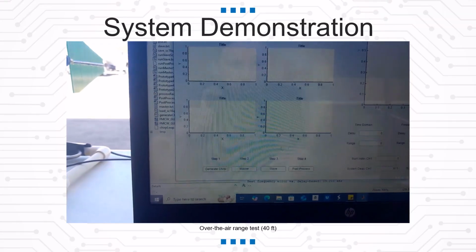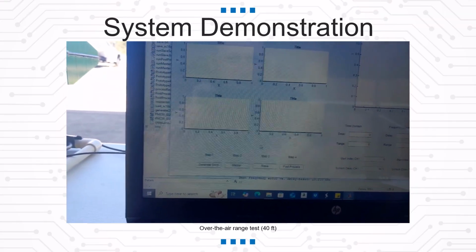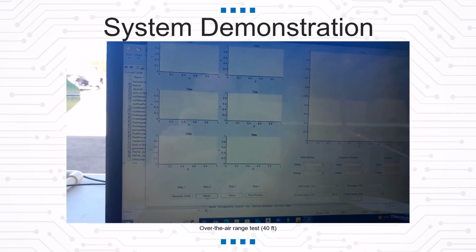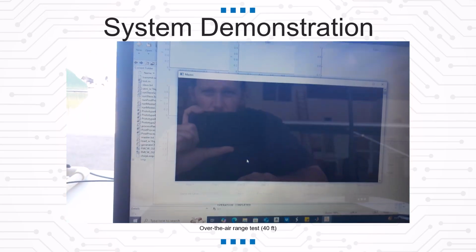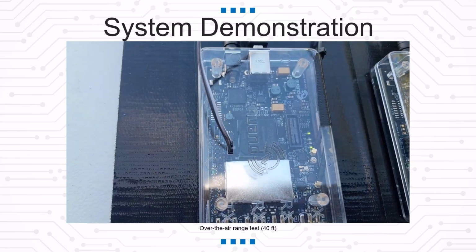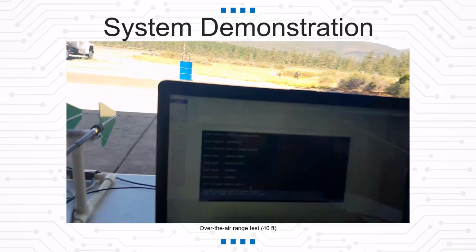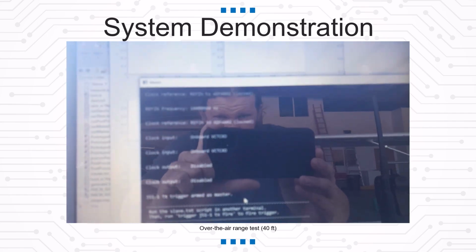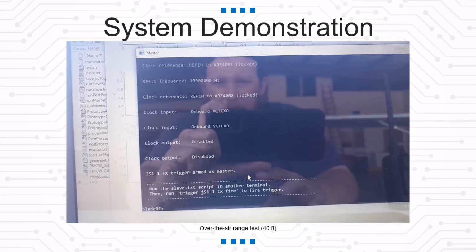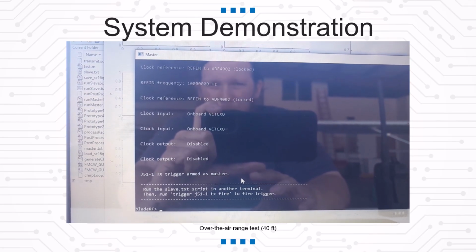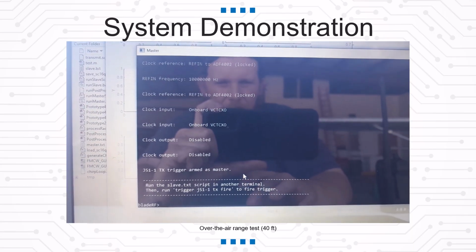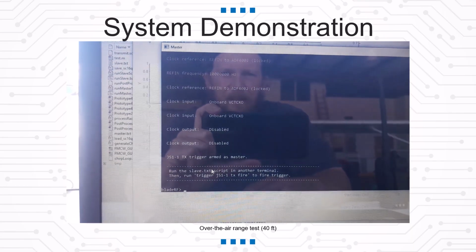So by generating the chirp, we create the SC16Q11 file. It's a binary file for saving IQ signals. And then we can run the master script, which we can see the light is starting to run on the master module. So this sets the center frequency, bandwidth, gain, locks onto the reference oscillator, and it's initializing the trigger.